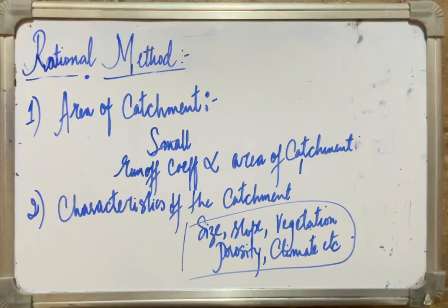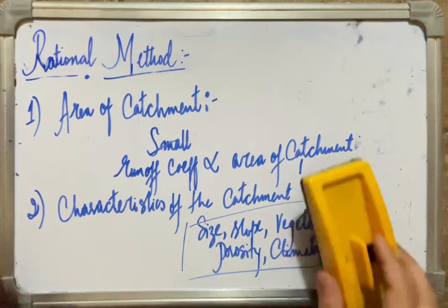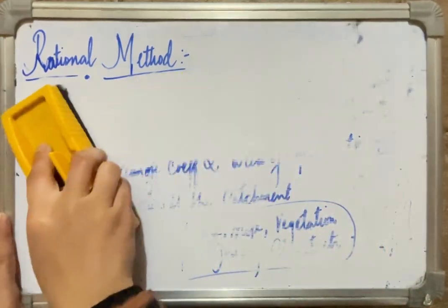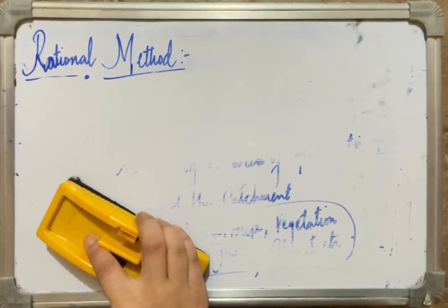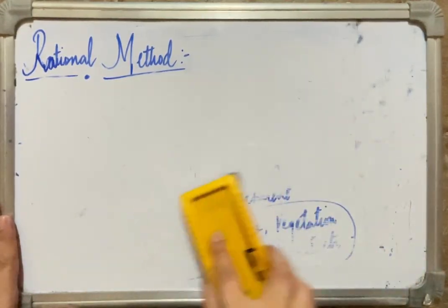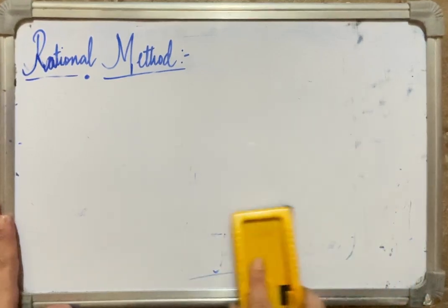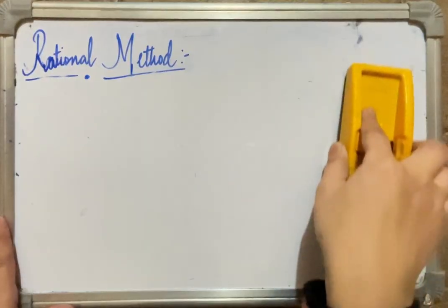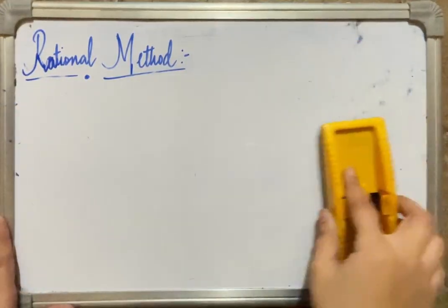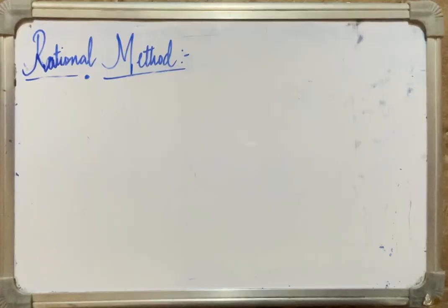All right. The next factor which affects our runoff coefficient is the condition of ground at the time of rainfall. Let me rub it first and then we'll go on studying it. Runoff coefficient is a ratio between surface runoff to the total rainfall in that particular area, in a fixed interval of time. It varies generally from 0.20 to 0.70, and its selection should be done carefully.